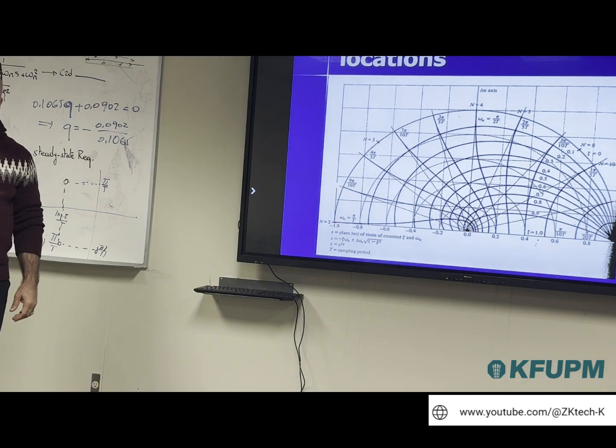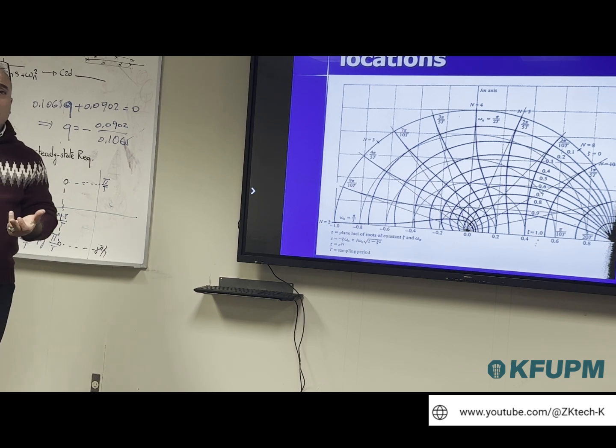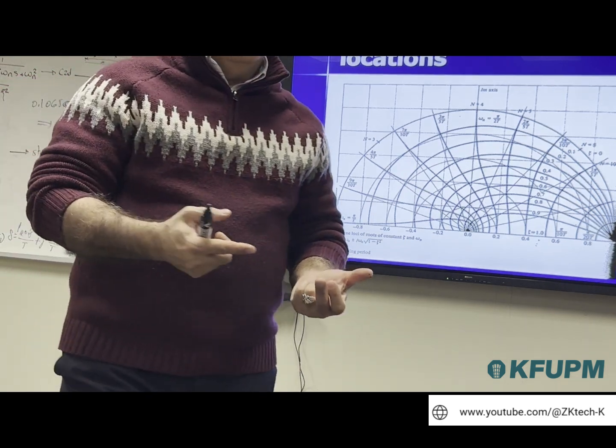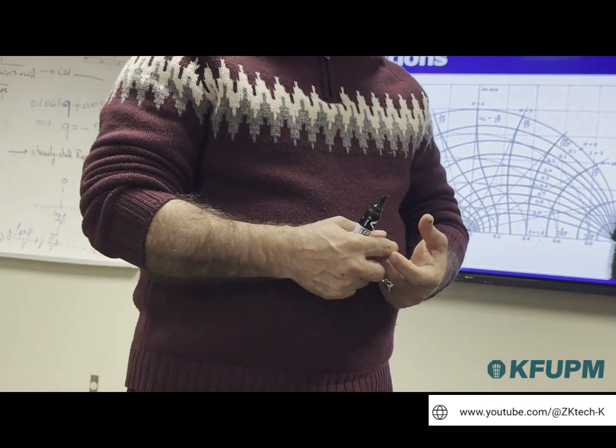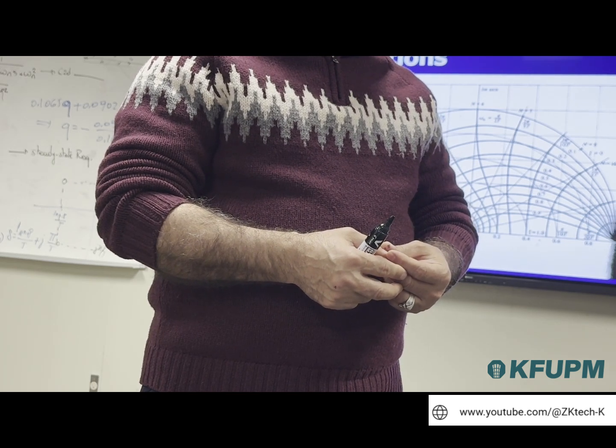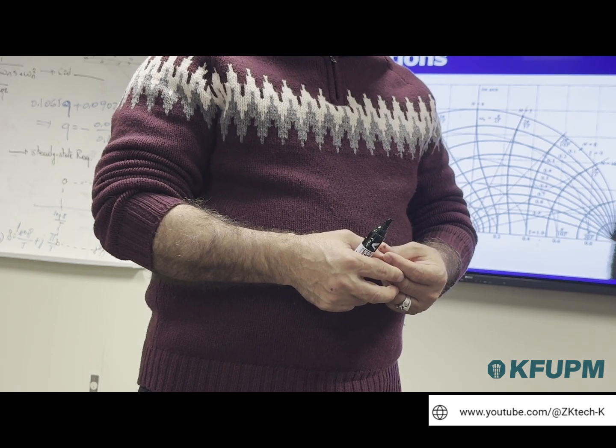Initially, when we look at the system, it was 1 over s times s plus 4. There was no zero in the system. We convert it into the discrete and then the zero appears. So this zero appears due to the sampling period or sampling time, and due to the method of discretization that we are using. But initially we don't have any zero. Did we create our own zeros, or is it a real dynamic of our system?